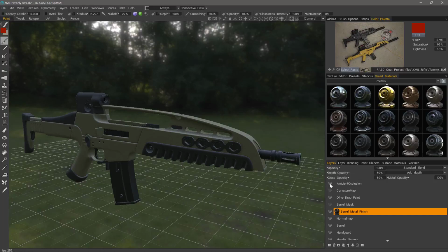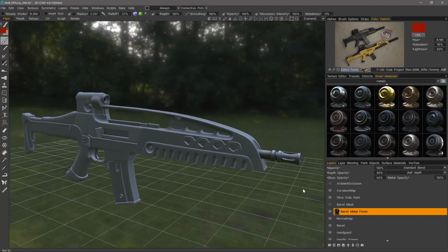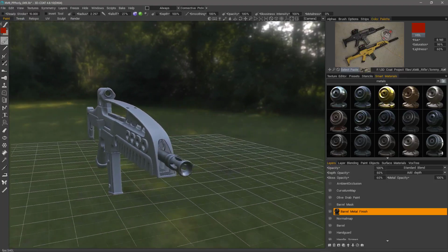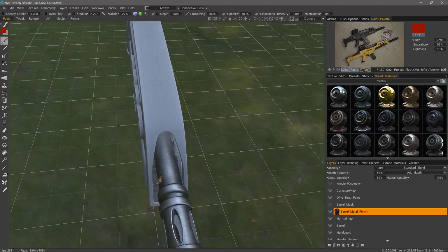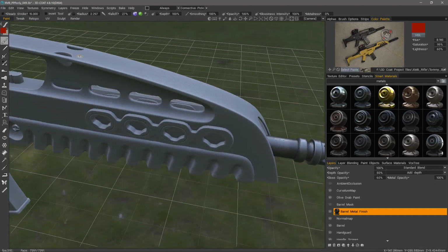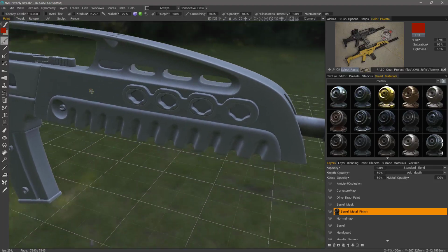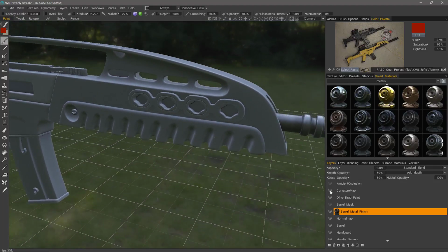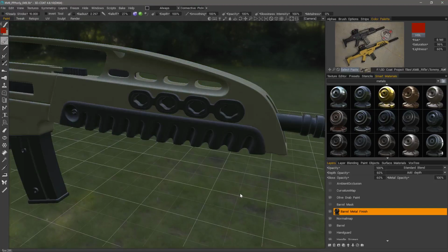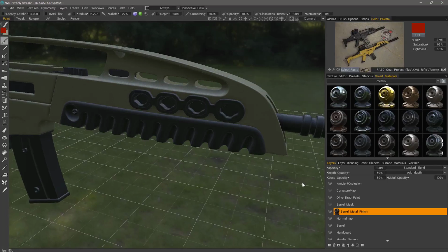Let me hide the ambient occlusion layer, and I will unhide the curvature map. With that visible, you'll notice that in the baking process, it creates lighter grayscale values in the convex areas of the surface, darker values in the concave areas, and medium values in the flat or low curvature areas. So again, this is just something for 3D Coat to read internally. You can also export it for your game engine if needed. I'll unhide our ambient occlusion map.